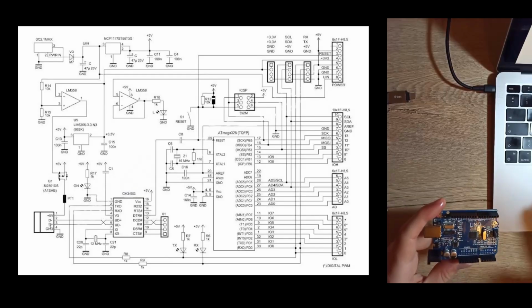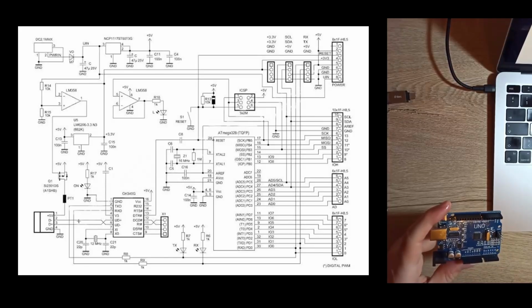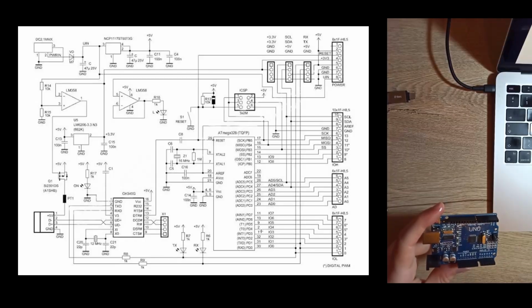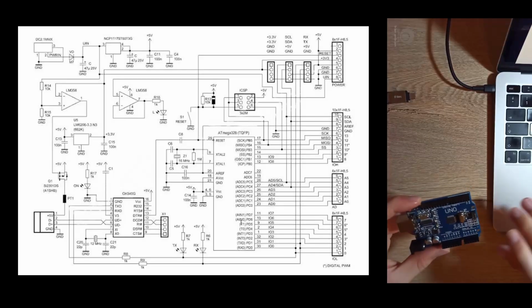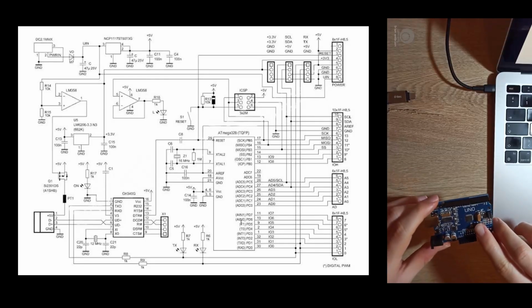It just converts USB data to our UART data, right? So with the cables, you can trace the cables and you can see the data pins connect to here, and then the UART pins, TX, RX, are actually connected to the microchip directly, almost directly. We just got like resistors here, something. All right, so that's the communication, but we also need a way to actually program the memory here.